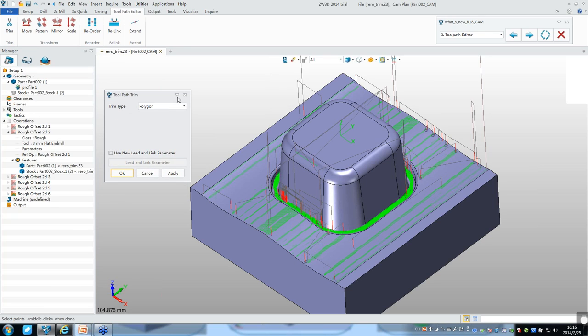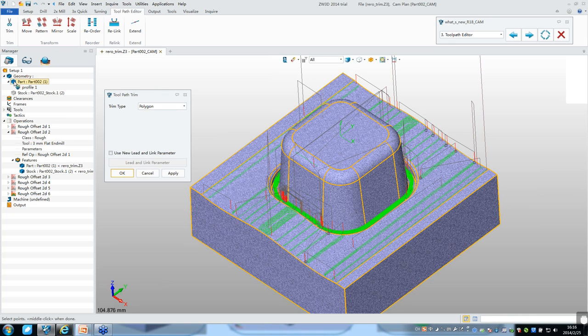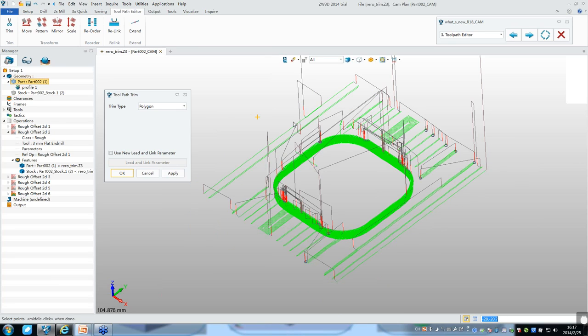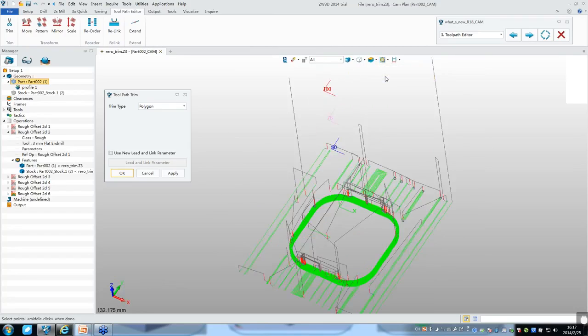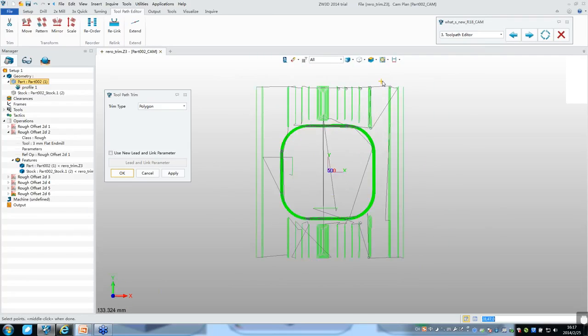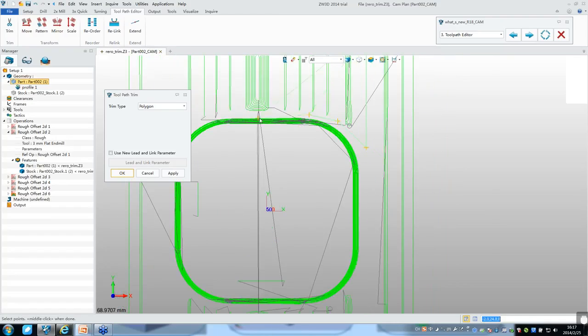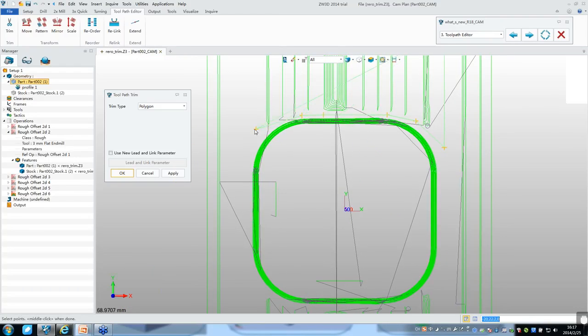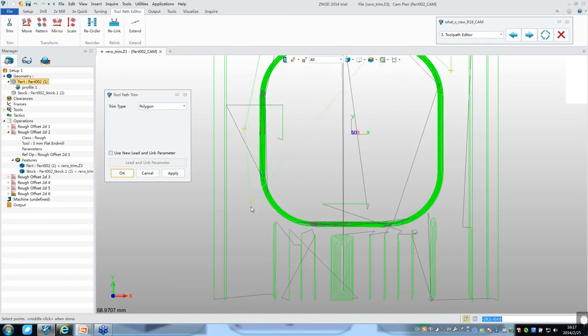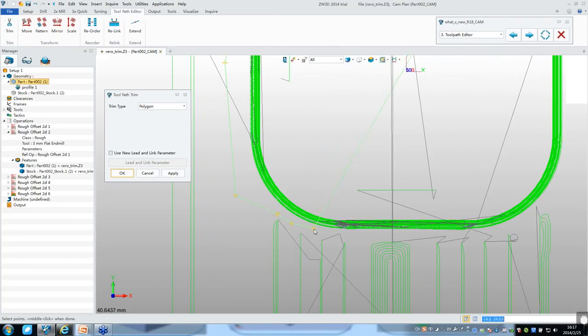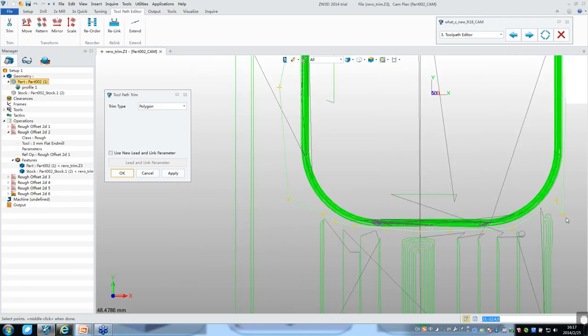In order to get a clear idea about where I want to choose, I will first hide this part and just leave the Toolpath in the blank area. Then let's align our view to the top view, and then go to move. Just like you draw a box, all the Toolpaths within this box will be trimmed.